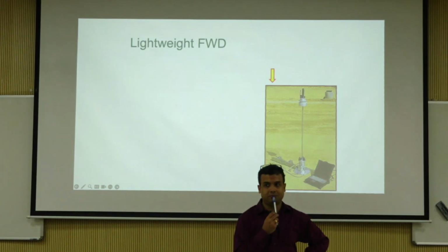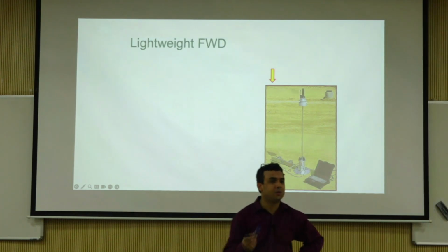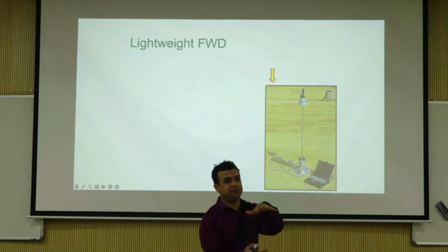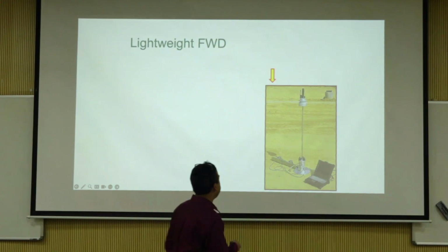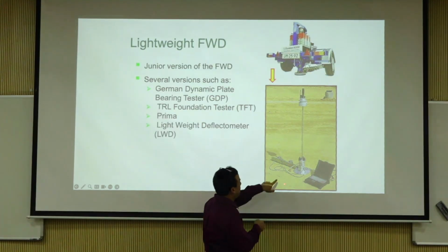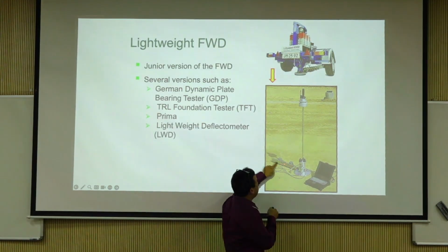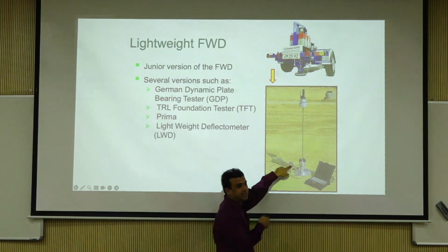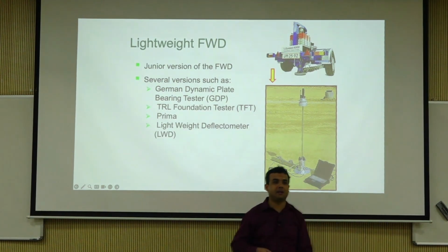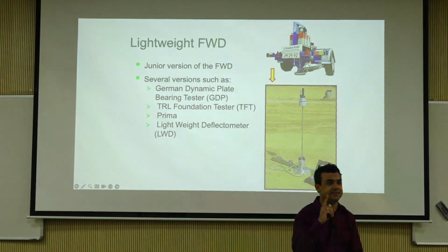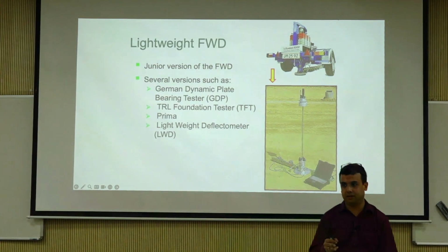No. It's a combination of everything. So what you calculate is something called E foundation or something. It's a composite modulus. There are abilities to extend it like this, offset sensors that you can do, and then some back calculation, but most of them have only one central deflection. You do it and then you measure.